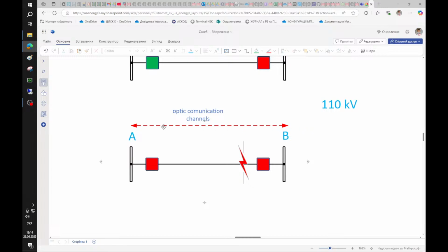It was damaged, restored, but not checked, and on the record from substation A side we will see that the currents from the opposite side are present in the record, but as I already said, differential protection was not in service. Also, I want to add that on that side there are no voltage transformers on the line. The voltage transformer is only on the bus.